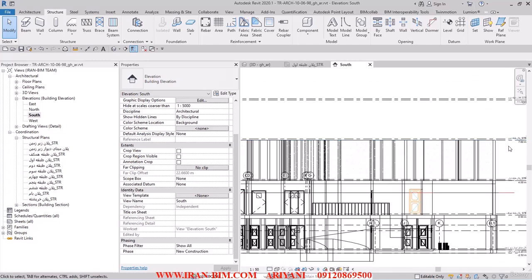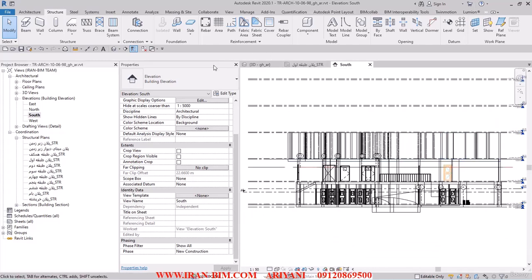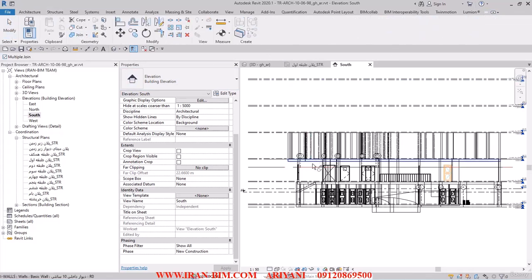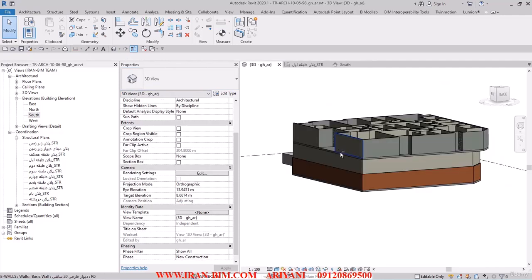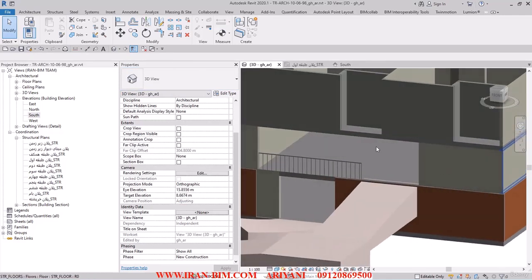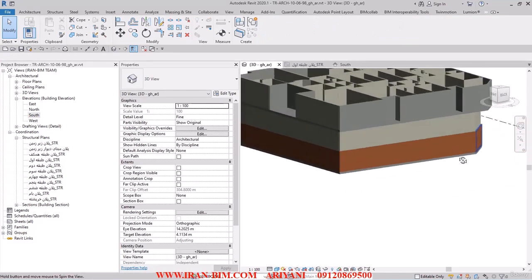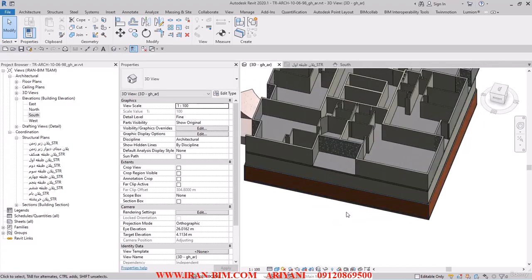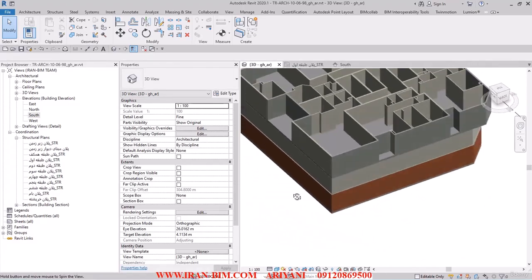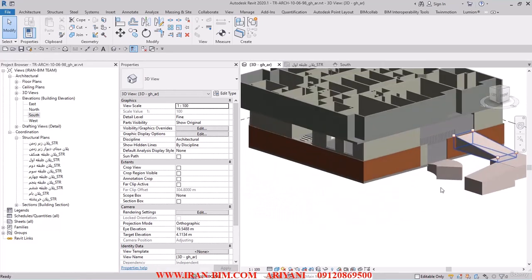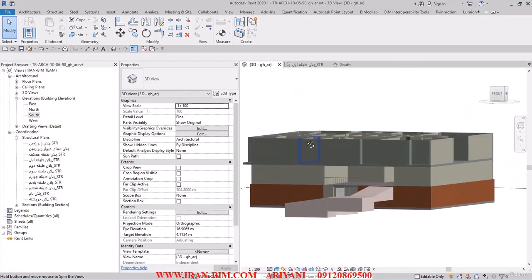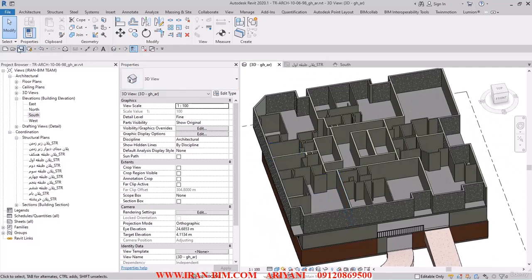So from the modify section, I'm going to use the join tool and check the multiple joint box. Then I'm going to select the base, and then I'm going to connect these like this. And there we go. And if we take a look at the 3D view, the walls have been joined. These excess areas that we see in the 3D view are no problem, and then later when we get to the joinery, they'll get fixed themselves. As you can see, this is how it turns out, and it's all okay up to this point. So I'm just going to take a quick save of it.